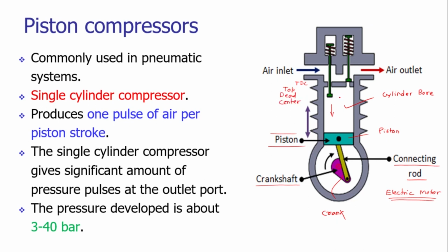So there is the creation of vacuum here, there is a creation of pressure difference from the atmospheric pressure, and due to that the valve will get opened, and when the valve gets opened, the air will be sucked inside the volume for the half rotation of the crank.